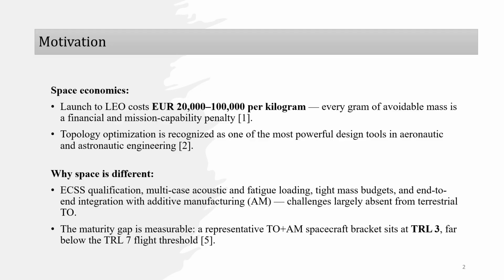However, space topology optimization is not just a lightweighting exercise. Space components must satisfy stress, displacement, vibration, fatigue, and multiple load case requirements. They also need to pass qualification procedures, often following ECSS standards.